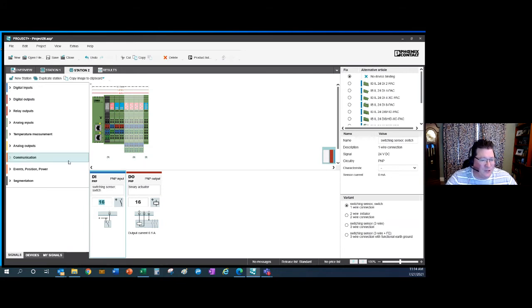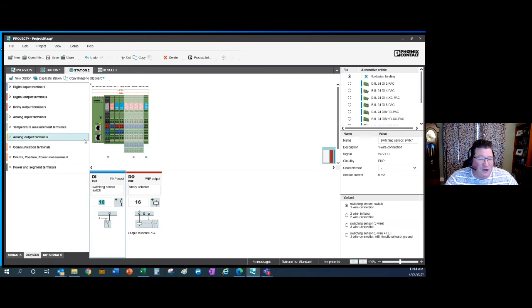And then, of course, the other feature with the inline, there's a little bit more in the rules of what you have to follow as to how many modules you can plug together versus current draw, so that if you're drawing too much current on the outputs, you may have to insert power modules.